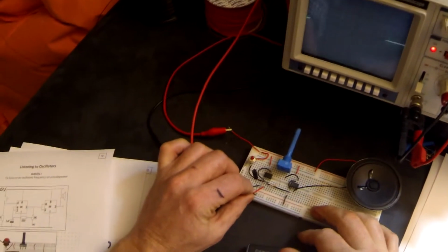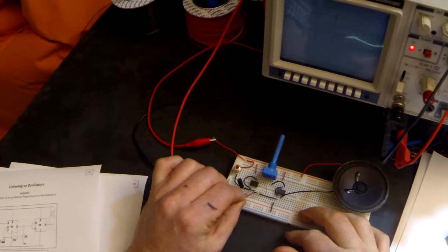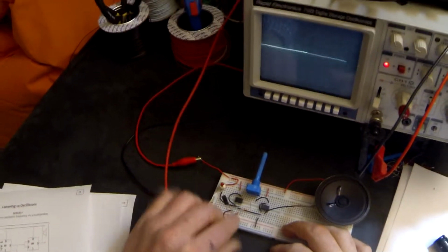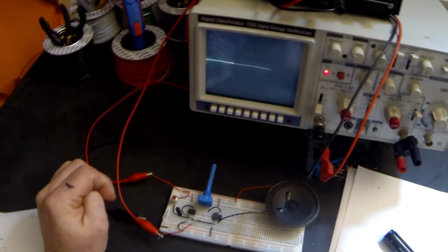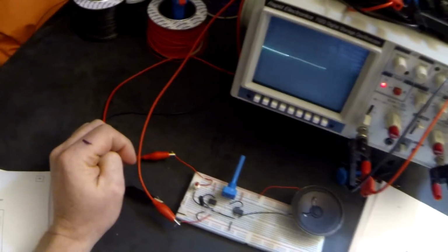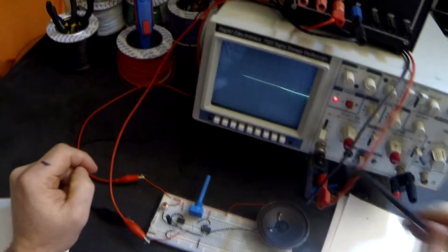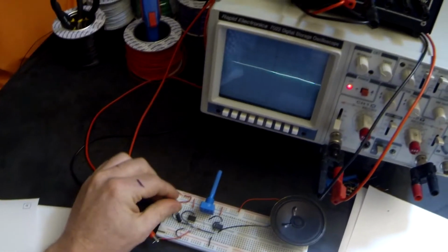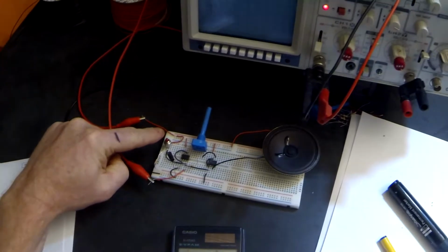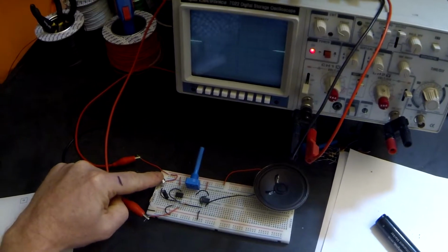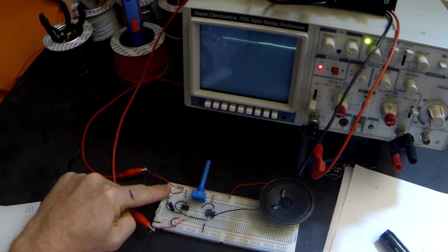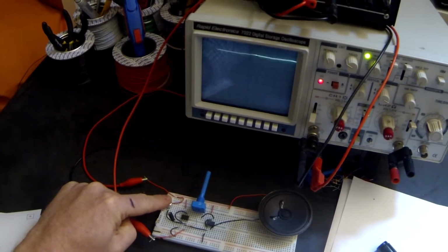And we can do that using the oscilloscope rather than a voltmeter. So if I connect my oscilloscope to pin 4, at the moment you can see that this is set at 0 volts. If I just put that on the ground, you can see the line is in the middle. So therefore DC must be 0. As soon as I press my switch, go, you can see that pin 4 goes high.